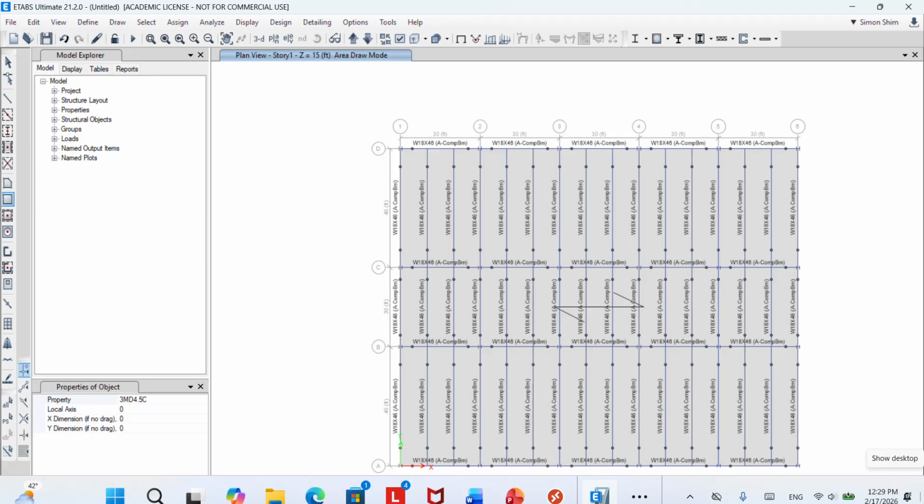Physically, if you rotate it and put it here, the corrugation has no stiffness, and it's going to fall down. So when you place metal deck, this arrow should be perpendicular.